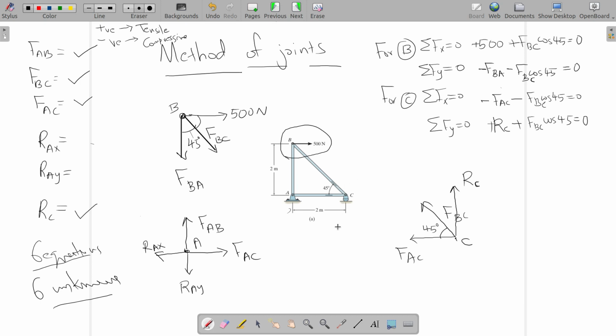Anyway, but you can take an upward or downward direction and get the correct answer, no issue. So if RC is positive, its assumed direction is correct. If you have taken RC downwards, you will get it as negative, and so you can correct the direction here, or you can simply write down negative values for reaction, which simply means that direction is opposite.